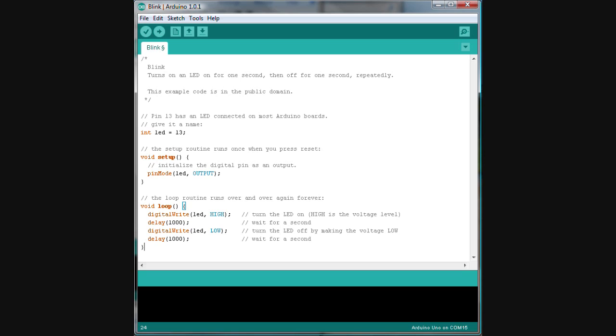So now I have another quiz for you here, and this one hopefully won't take you too long, but I want you to modify the blink code that we have here to print out 5 volts right after we do digitalWrite HIGH, and to print out 0 volts after we do digitalWrite LOW. So you'll need to make some modifications to setup and void loop, but again, it should print out the words 5 volts after digitalWrite HIGH, and then 0 volts after digitalWrite LOW down here.